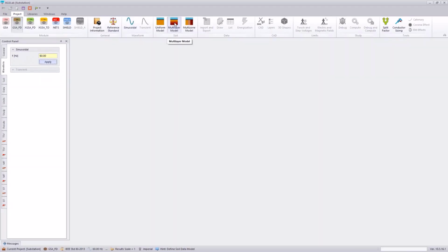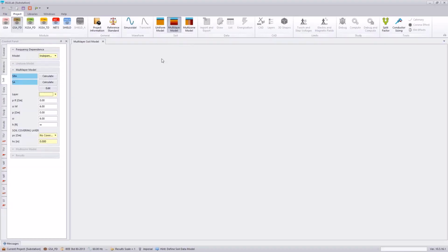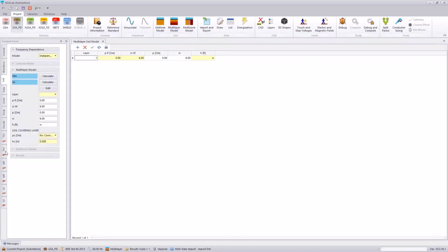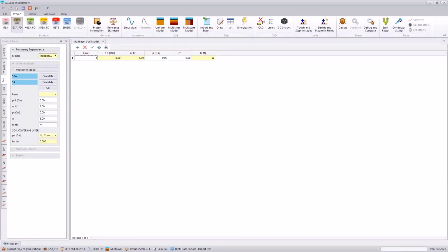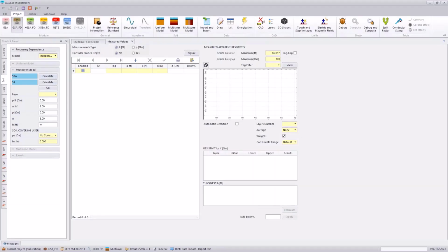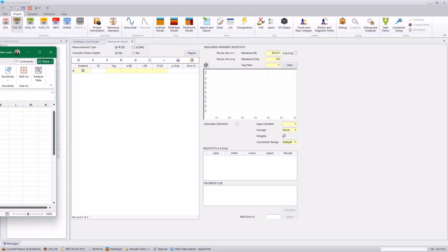We need to, just like with the normal substation analysis, create our soil model, which is typically derived from soil resistivity information. If you need more information on that, I highly recommend reviewing the IEEE Standard 81. That's kind of the sister guide of IEEE Standard 80. It provides all the measurement techniques related to grounding systems.